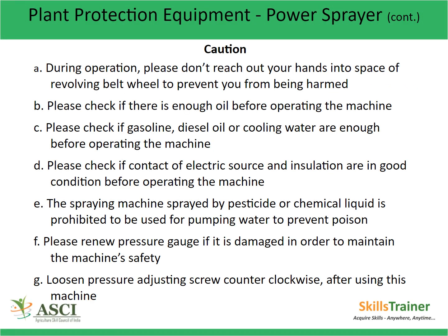Caution: during operation, please don't reach your hands into the space of the revolving belt wheel to prevent you from being harmed. Please check if there is enough oil before operating the machine. Please check if gasoline, diesel oil, or cooling water are enough before operating the machine. Please check if contact of electric source and insulation are in good condition before operating the machine.